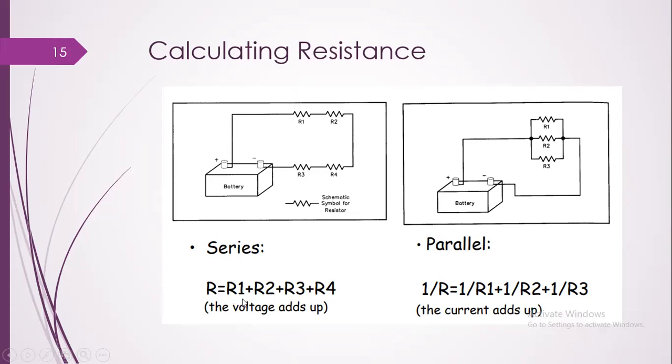The equivalent or total resistance of the series can be found by the formula R equivalent equals R1 plus R2 plus R3 plus R4, and the voltages add up as well in this combination. Another way to say it is that the total voltage is divided among the individual resistances. So voltage is divided in the series combination of resistances in this scheme.